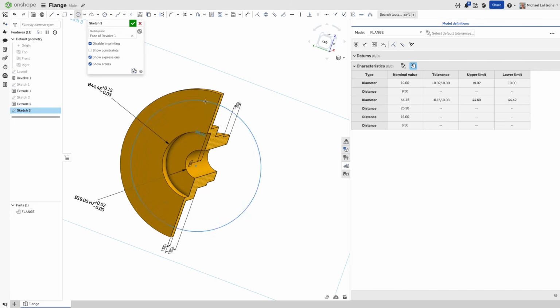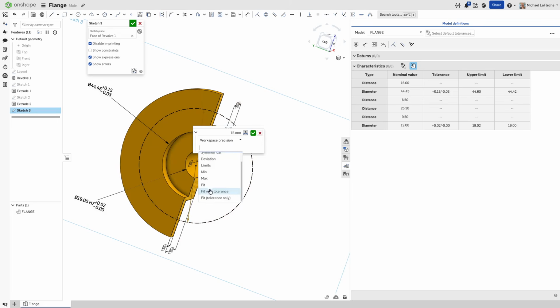All right, I'm doing some lineup work now. You can use traditional Onshape relations like coincident and parallel. There are buttons for them at the top of the inspection panel to help lay out your dimensions in a way that's visually pleasing, because we're not creating a drawing here. We're creating views essentially of a 3D model with the information that we want.